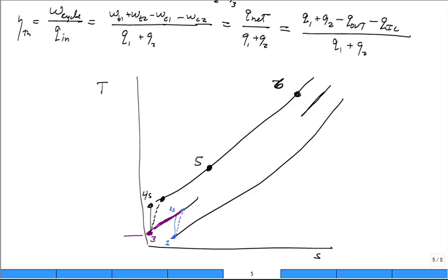Now it expands isentropically through the first turbine to 7s, but if there are some irreversibilities, 7 actual. We pass it into another burner for reheat, which brings it up to this temperature at 8, often the same as the temperature at 6, but at a lower pressure. Pass it through the second turbine stage to 9s, or 9 actual.